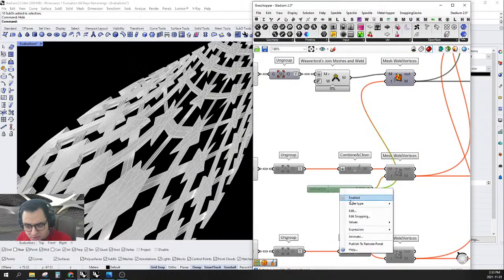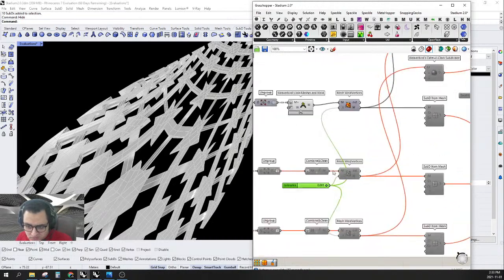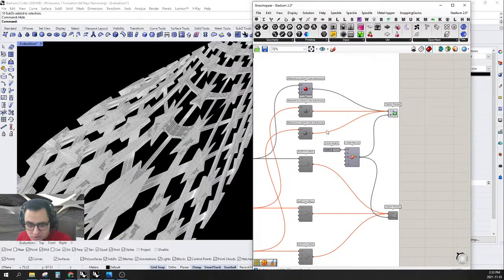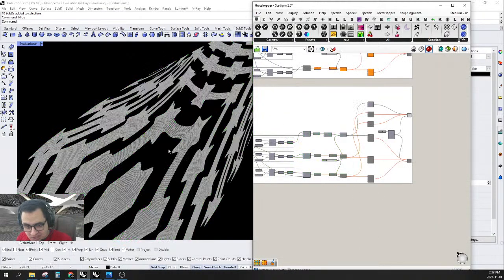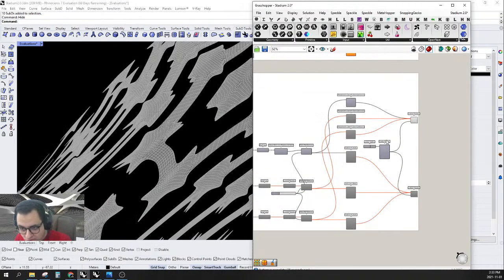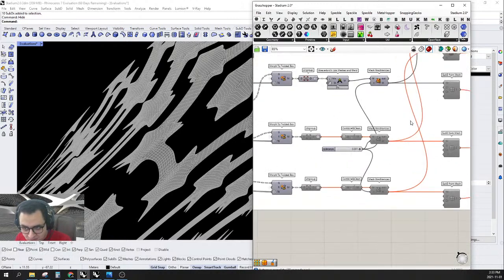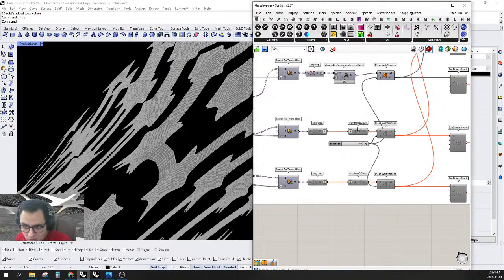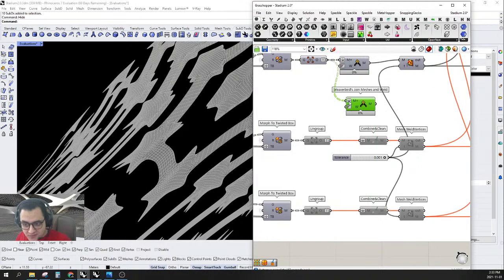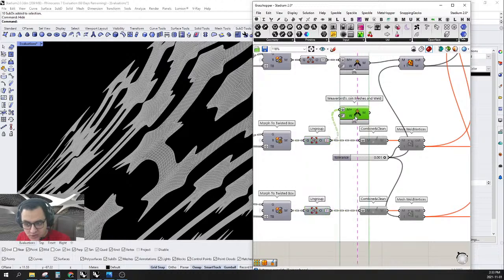Aha, we need to enable this because this one is the tolerance, and now this should be working. Enable both of these. Preview on, and now we should have perfectly clean meshes. Of course, we can increase the number, which we will do in a moment, but after we fix whatever happens in here. Yeah, let's select this, Control C, Control V, and enable those. Import this one in here. Okay, and import this one in here.